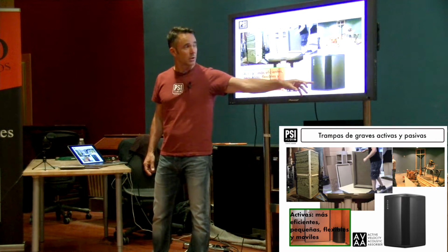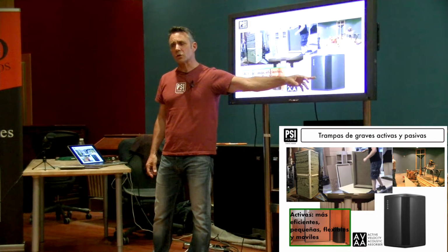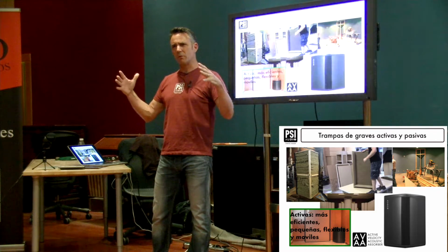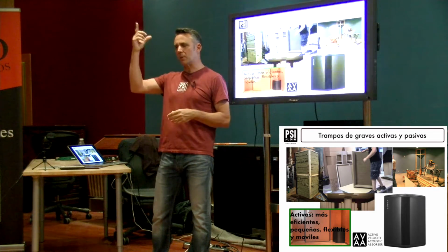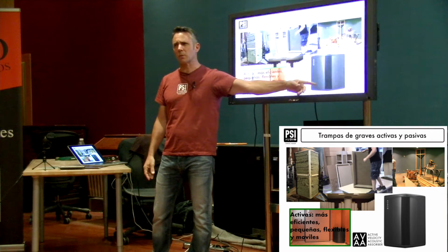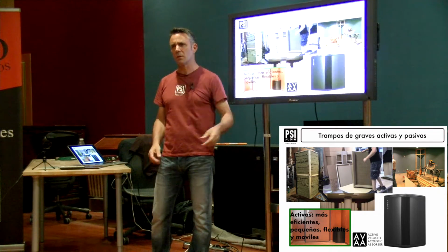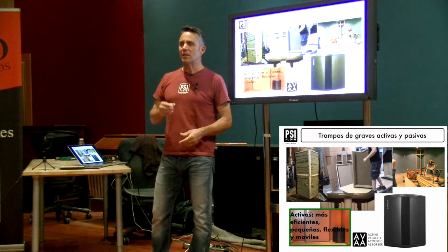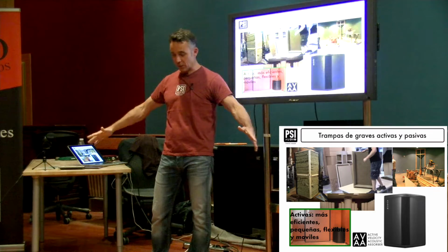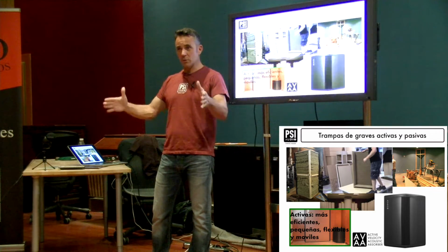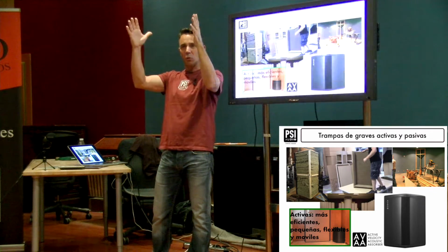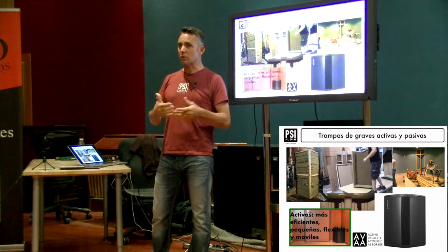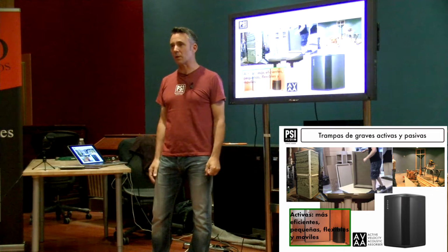Just for your information, we have also sold some that we put in boiler rooms and heat pump rooms, where the hum of the machinery is disturbing the people above, and that gets rid of it properly. In the hospital in Geneva, they have some in all their technical rooms. And in flats in London built above the underground, the sound comes up in the solid walls and then generates noise inside the room that excites the room modes. We got 6 dB reduction on these modes in these flats in London.